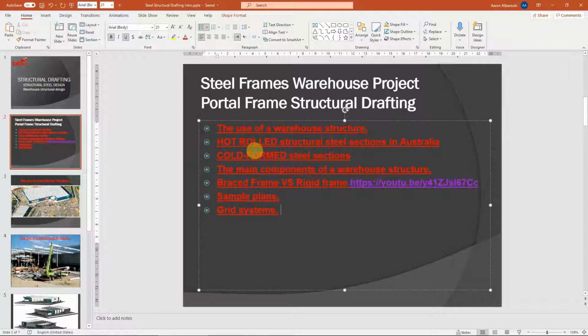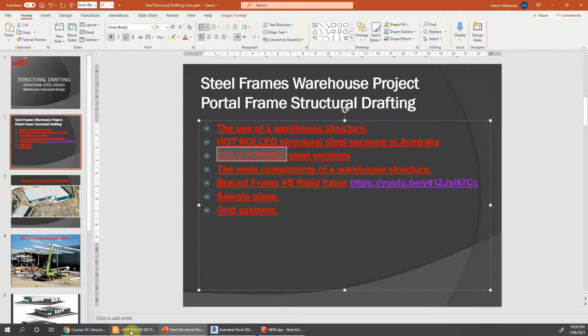So of the two types of steel, we've got the hot rolled type of steel and cold formed members. For hot rolled, usually they have to heat the steel to a point where it's red hot, so they can form it into shape. For cold formed steel, they use thin plates and they bend these plates to shape the structural members, and that's why we call it cold formed. They form it while it's cold, without heating. Maybe it's important for you to search this type of material or the difference between them. Going back to our